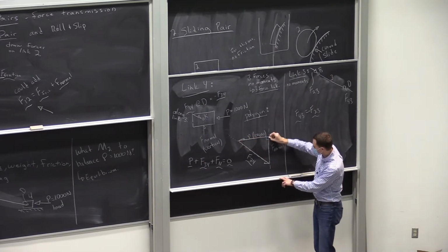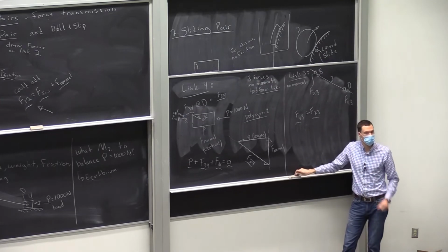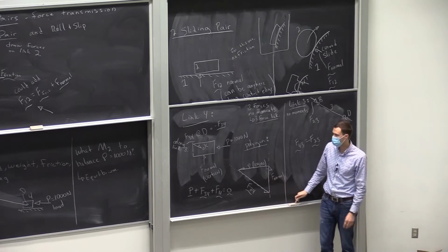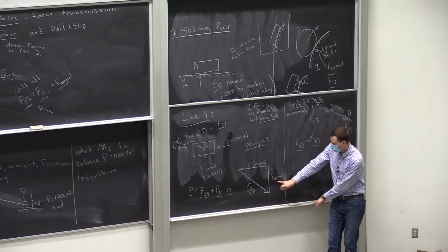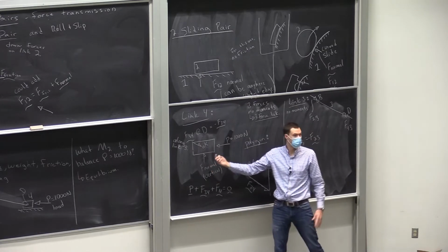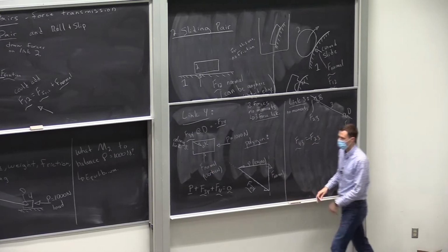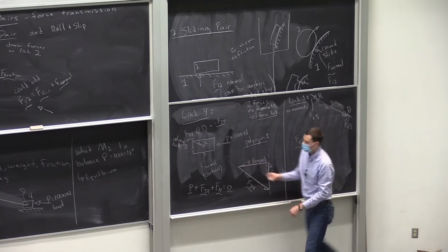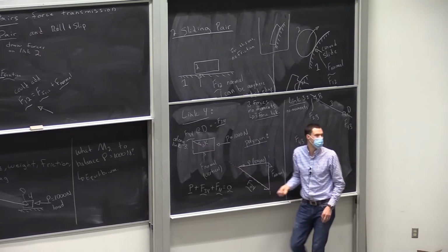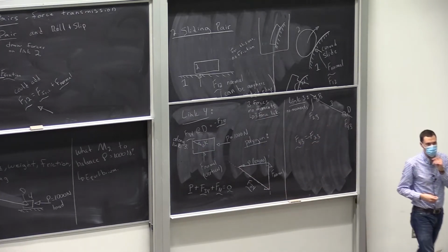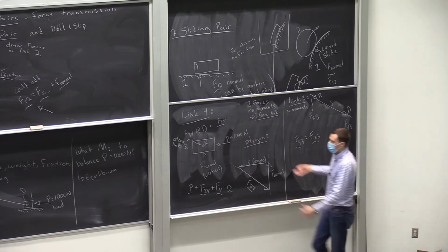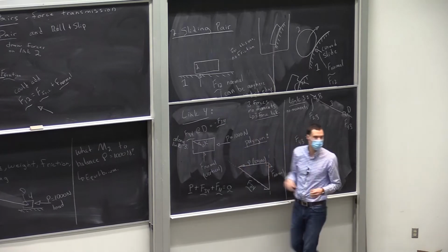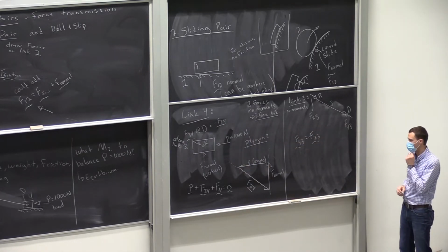So we can put the arrowheads on these other two, and we can get the directions. Okay, so at this point, now we're able to check if I put some of those on correctly. Normal force should be up. I drew it right. Otherwise maybe we would choose to correct that one. F3/4 is down to the right along link 3. I drew that one right as well. And as you solve a few problems, you'll get better at guessing those, so you don't have to correct them. You know, it needs to balance. P was pointing to the left. Something needs to point to the right to balance it. So you'll get better at identifying those right off the bat.